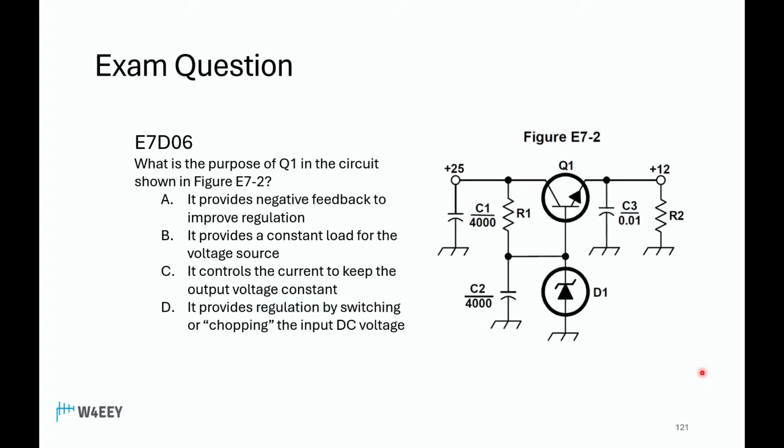All right, so some questions about linear voltage regulators. What is the purpose of Q1? It's this thing right here. Some tempting answers in there that are wrong. Delta. Charlie. Charlie, it is. Controls the current to keep the output voltage constant. Yeah, the switching and chopping applies to a switch mode power supply. This is a linear voltage regulator.